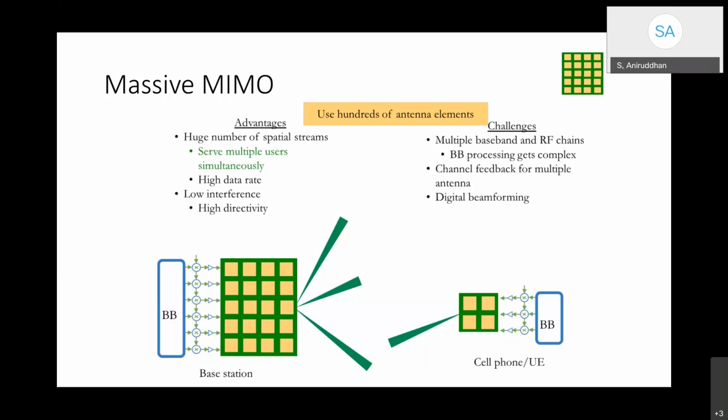specific direction. Now, as you might imagine, having 1024 streams of data, 1024 antennas, 1024 radios, power amplifiers, etc., the hardware gets very complicated very quickly. So I don't expect most people to implement 1024 antennas, but probably stop at about 256, at least in the first try. Obviously, all of this is on the base station. On the cell phone side, you may have a maximum of maybe 4 antennas and 4 systems. So that will already give you a lot of gain over the traditional LTE.